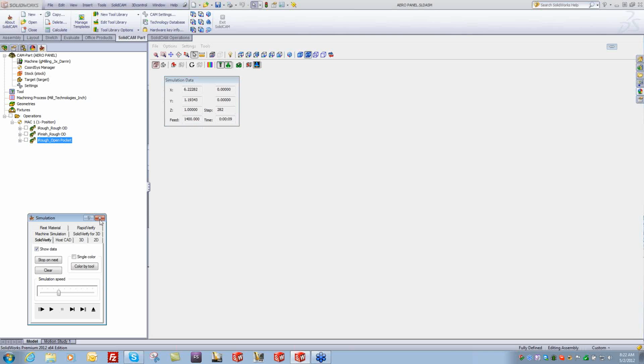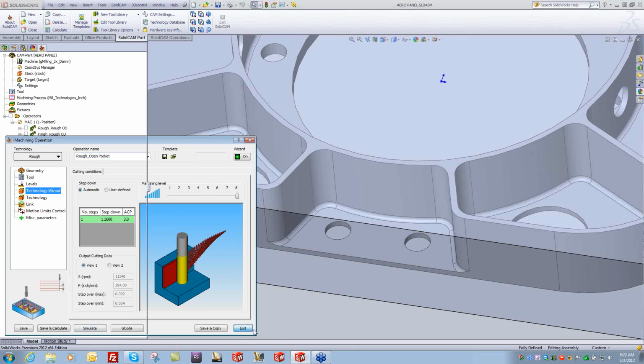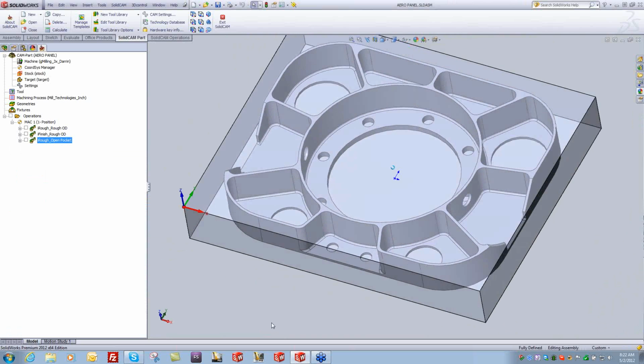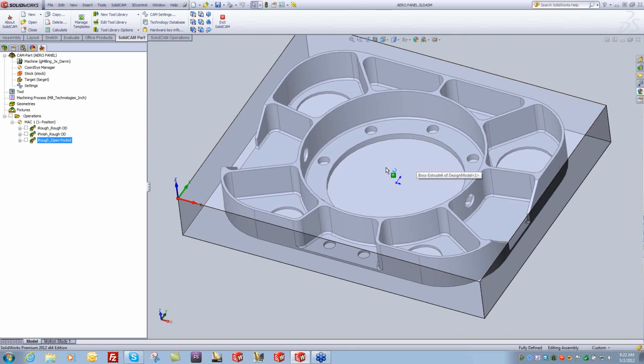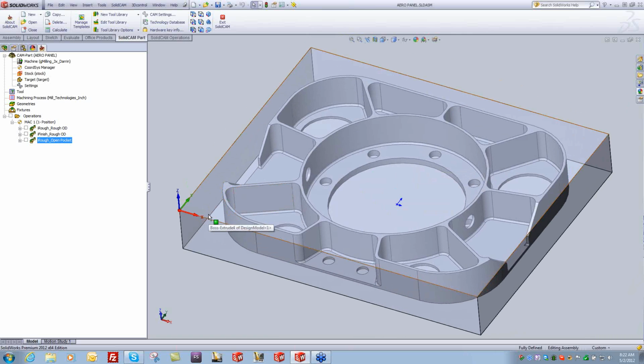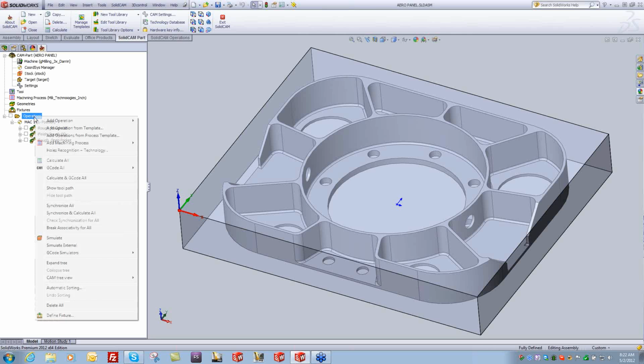All right. Let's go ahead and create a rough for the inside here. Now, because we're working on the inside of the part, the chains have to be opposite. Normally, when you're working from the outside in, you always start with the open edge pocket first, and then the closed edge. But when you're working on the inside of the part, you need to start with the closed edge and then the open edge. So what we'll do is we'll create a new iMachining toolpath.